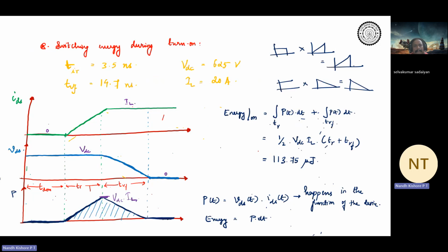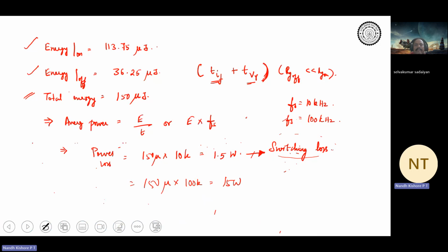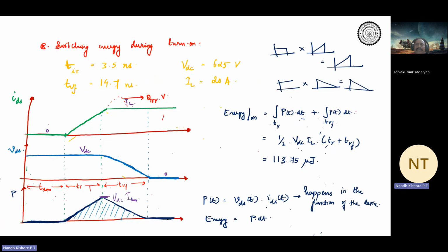This is just voltage and current we have taken. But as I was telling you previously, the current will also have reverse recovery. In this problem they have not given it, but if they give the reverse recovery, they will give QRR. Energy is basically QRR into voltage, so that will be the energy. So in the turn on energy, you will add the reverse recovery component, QRR into voltage.